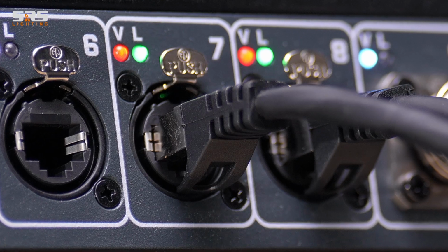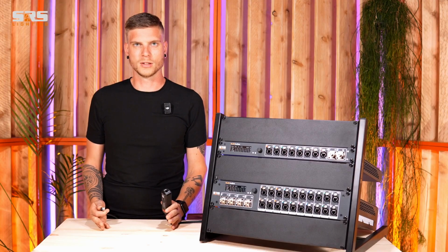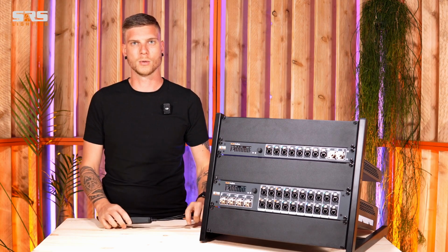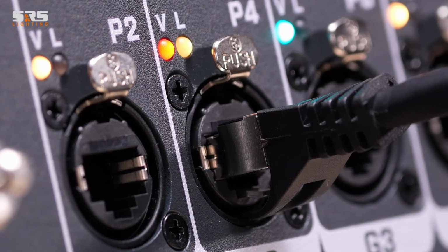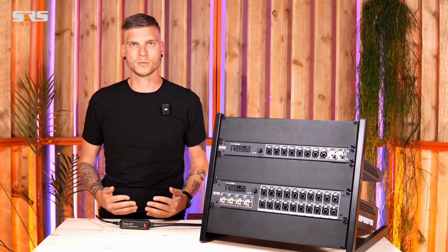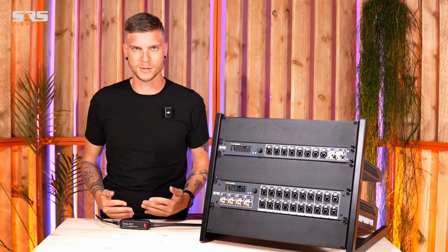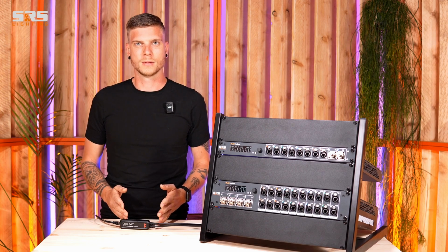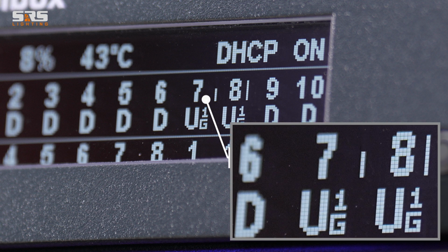When the port is green, it is up, if power over Ethernet is being used. As with this Dante adapter, the switch will indicate that power is being sent out by displaying an orange color on the right LED. If the LED turns light blue, it means that the port load of 85% on that specific port has been exceeded. The port can handle a data load of 1 gigabyte per second. You can see that the load is increasing at the points that are growing.